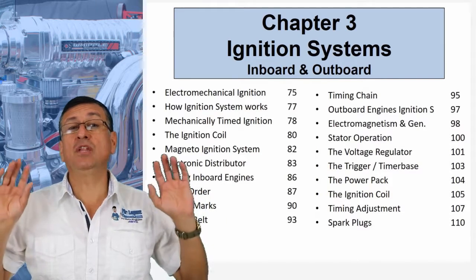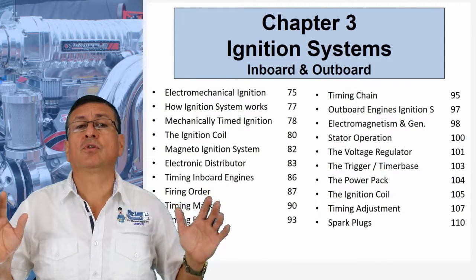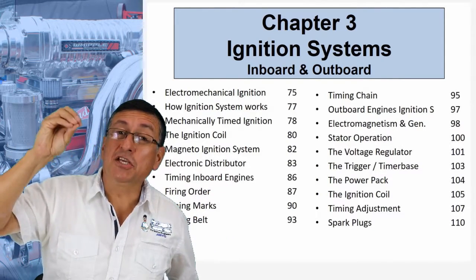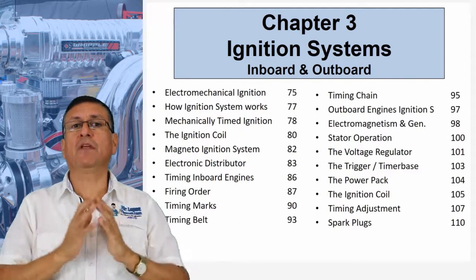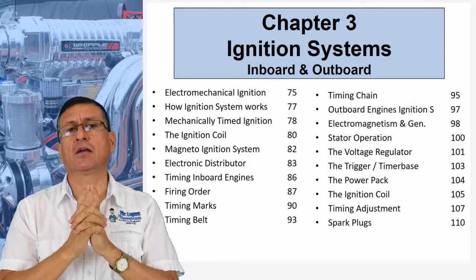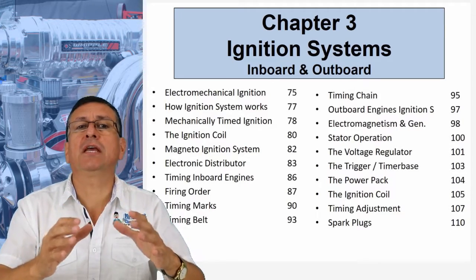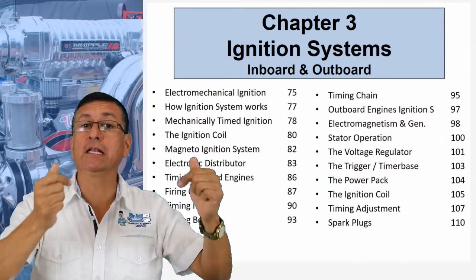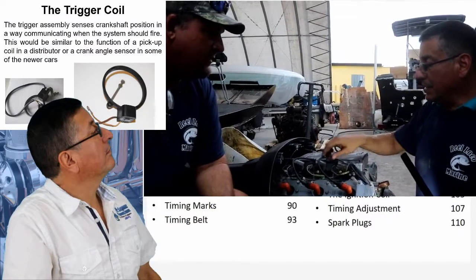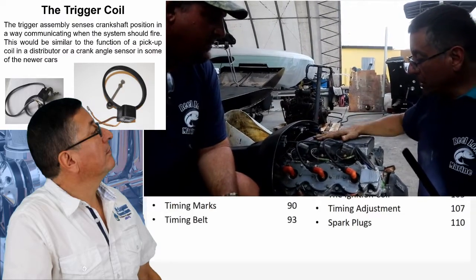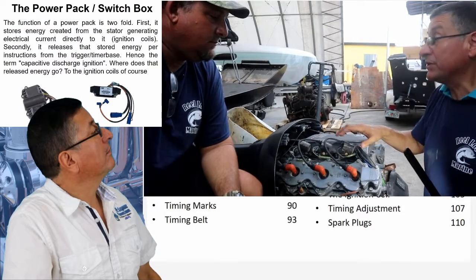In a two-stroke engine, basically, if the engine is direct fuel injection, you need to control the moment of the injection of the fuel, and the moment of the spark. Both of them are controlled by the computer. For that reason, the relation between the computer and the coils with the spark plug is important. Danny, it's a special relation between the computer, the coils, and the spark plugs. In this particular engine, in this particular example, it is critical, no?